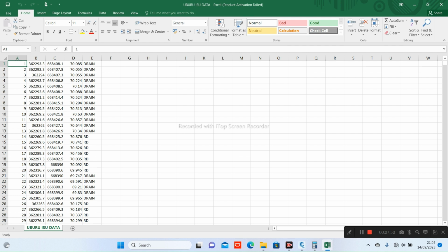So we have the easting, we have the northern. The surveyor has to tell you which column is the easting, which column is the northern. Here in Nigeria, most times the way we know it is the easting is always smaller, it's always less in digits than the northern. And sometimes even if they have the same number of digits, in terms of value, the easting is always smaller.